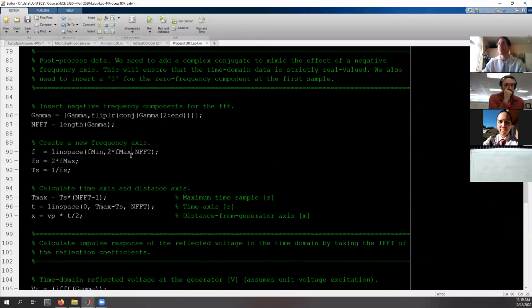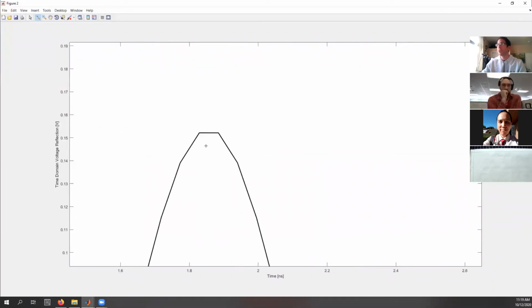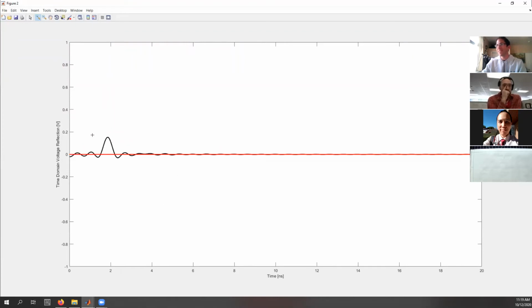So you'll notice the data is fine. It's just going to change the scale a bit like that, so kind of cut it down by a factor of 5 there. But you see how it's nice and smooth now, and you can see it's a very clear sinc function. So all we did was artificially increase our bandwidth by just stacking a bunch of zeros onto that reflection coefficient.